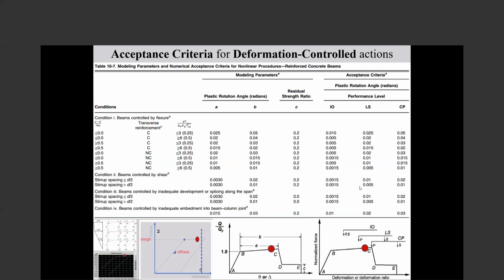Because of that, they generally limit the amount of axial force due to the earthquake, for example, 0.35. But for the smaller ones, there are a couple of modes of failure, and mainly in shear.